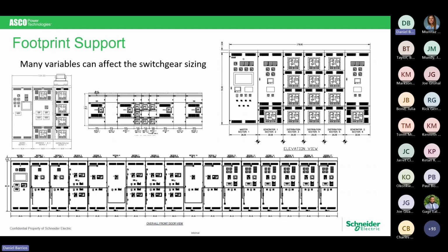Why are we trying to do that? It's pointed out in the next couple of slides. We are trying to minimize the amount of main bus. In the case of paralleling switchgear, we can go from 3,000 up to 10,000 amps per bus segment. Why do I say per bus segment? If you have more than that, I have a 10,000 amp segment. I have another 10,000 amp segment with maybe some type of a tiebreaker, 5 or 6,000 amps or so. But we are limited to 10,000 amps.